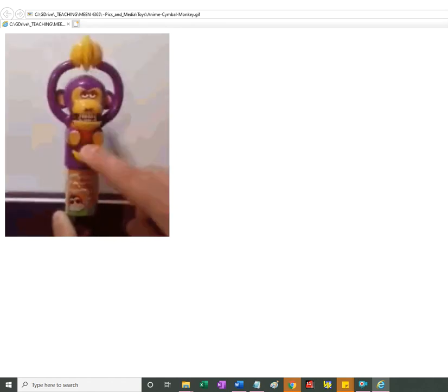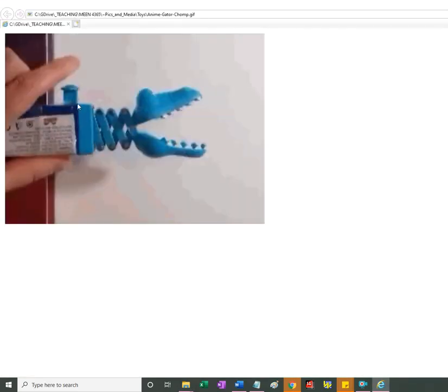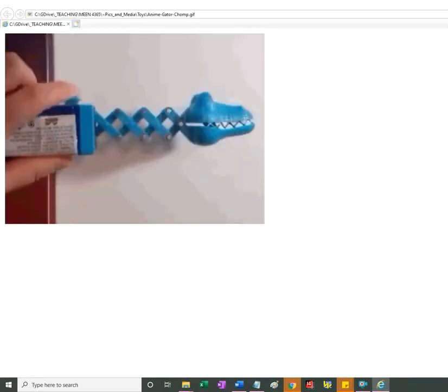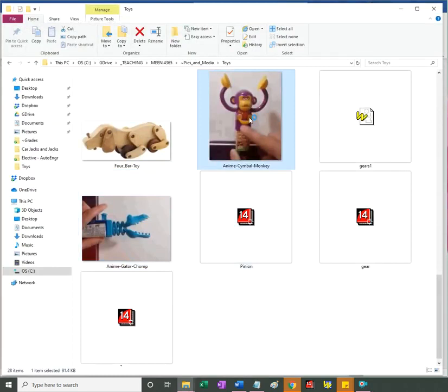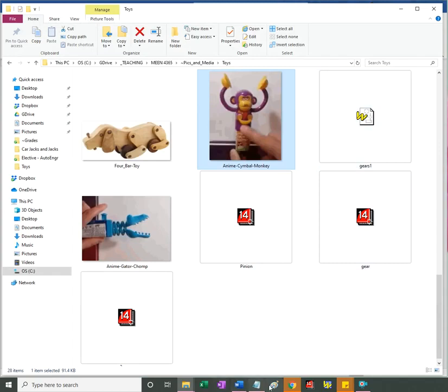So you do mobility analysis, making sure that you have 1 degree of freedom in both cases, because you have one input for both. Okay, button pressing and this banana being lowered, so both go with one input.